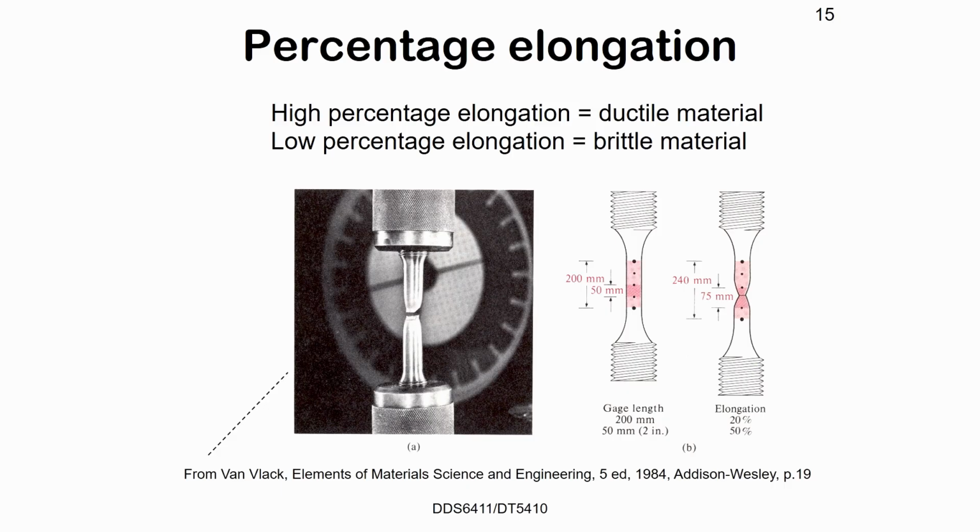So what's the difference between maximum strength and ultimate compressive versus ultimate tensile? It depends on the loading. If you are loading it by tension, you will break it by tension. But if you compress it, it will be reversed, a mirror image, because compressive stresses are negative. The shape may not be exactly the same when you mirror it.